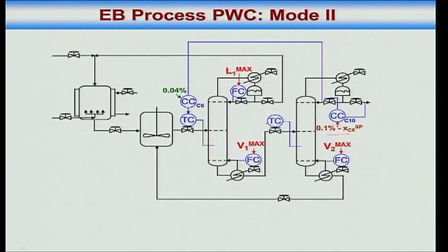Now that I have done this, I put in level controllers. Note that the reactor 2 outlet valve is taken. I have to control the level of the recycle column bottom. The only valve available is here. This valve will get used to control the level of this guy, right? So the only way to control level here is this way. The only way to control level in the first reactor is this way. The only way to control the temperature of the first reactor is this way. And of course these set points must be at max allowed. That's because my optimizer said so, and it makes physical sense actually. Yes or no? Okay, fair deal.